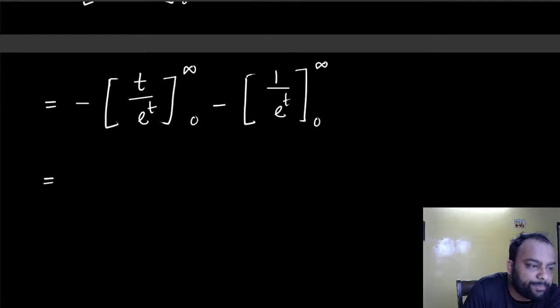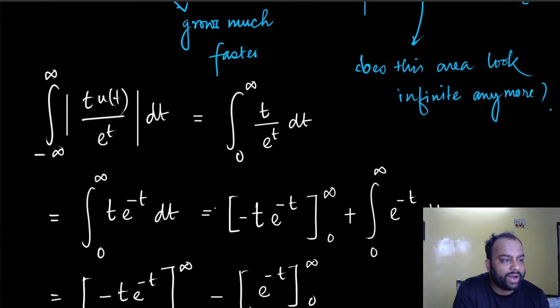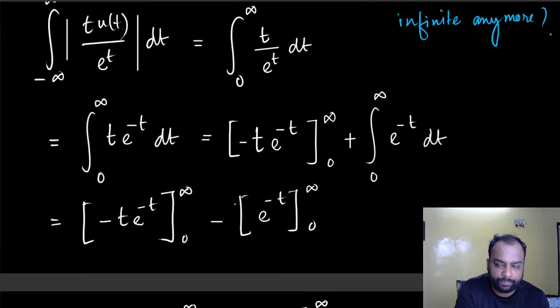All right. Somebody is asking something. No, you have just messed up the definition of ut. Why did ut go? Ut went into this story, right? So ut has a value of 0 when time is less than 0. So essentially in this integration, I have just reduced the lower limit from minus infinity to 0, because when t is negative, the value of this whole signal is 0 because of ut. That is where ut went. Ut has a value of 0 when t is less than 0, and afterwards it has a value of 1, right?